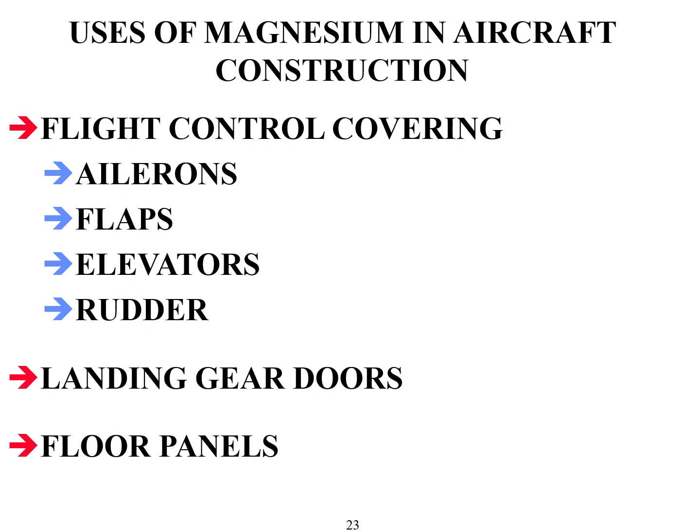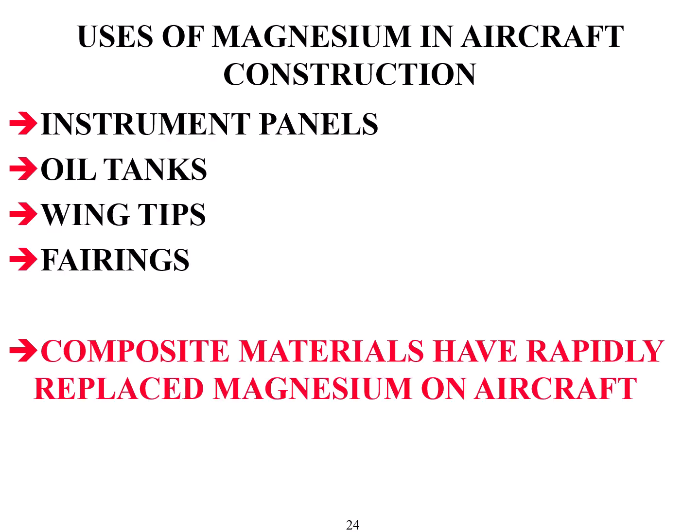But there are many aircraft still flying with magnesium flight controls, landing gear doors, floor panels, anywhere they needed a lightweight, rigid structure. For examples, and these are a little more enduring, instrument panels and tanks in general still tend to contain some magnesium because you can create such a lightweight reservoir with it.